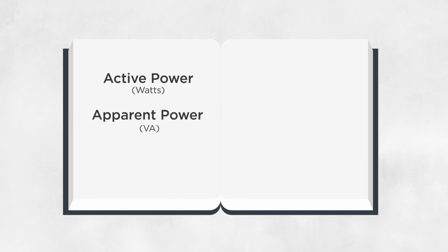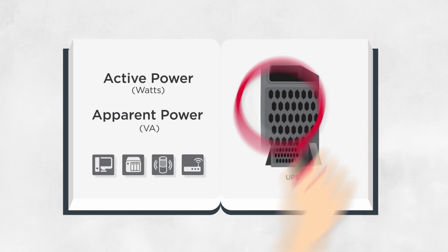Finally, as learned in this video, knowing the active and apparent power of your equipment will help you size the UPS correctly.